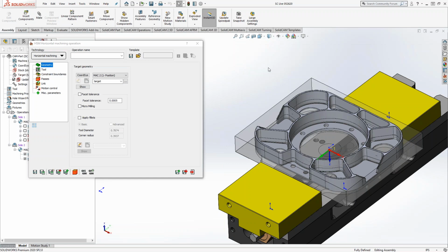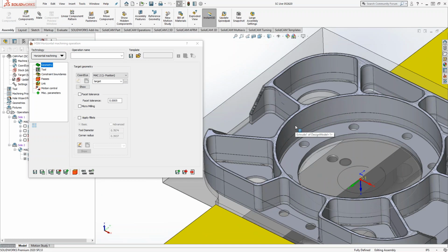Unless we're cutting into some very hard material, then we would have to do step downs. But with the horizontal, it's going to clean up all our flat floors and our flat walls for us, which is a real nice and easy way to do it. It'll clean up the walls only because if the tool is doing the floor and it gets close enough to the wall, then that's why it'll do the wall. It's not specifically designed to do the walls. It's just because this tool that we're about to use probably has enough reach and, like Kevin said, if the material yields itself to that, we can just do the wall as we're doing the floor.